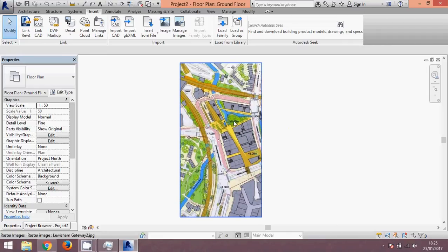You've got trees and foliage, and you've got buildings dotted throughout. Some of these buildings will be buildings that we will build and import into the drawing at a later point, and some of these, like up here, these houses, or down here, are not too important, so we'll add them as a conceptual mass. We want to show that there is a building there, but that they're not necessarily important to what we're doing.